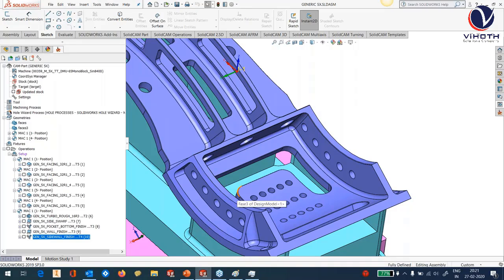I'm going to use barrel tools. What are the advantages of barrel tools? The biggest advantage with the barrel tool is that it has got a big radius, let's say a radius of 95 or even 100. And to get a similar scallop, let's say I want a scallop of 2 microns. If I want to get a similar scallop with a ball nose end mill of, let's say, 10 diameter or 12 diameter, I need to define a step down of anywhere between 0.1 to 0.2 millimeter to get that scallop. With a barrel tool, I can get the same scallop by going up to 1.1 millimeter to 1.5 millimeter depth of cut. So your machining time dramatically comes down.